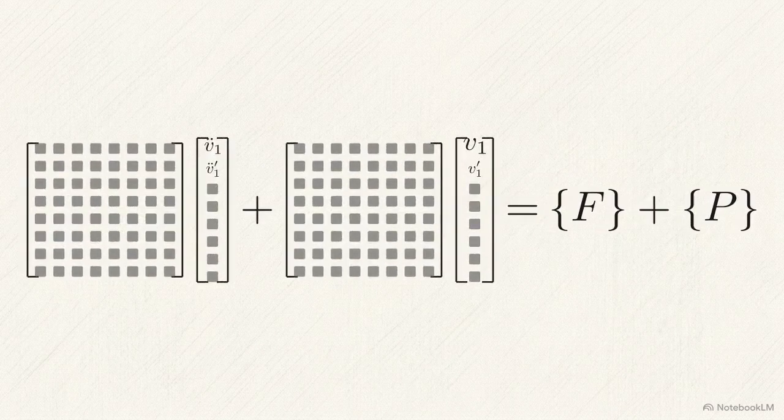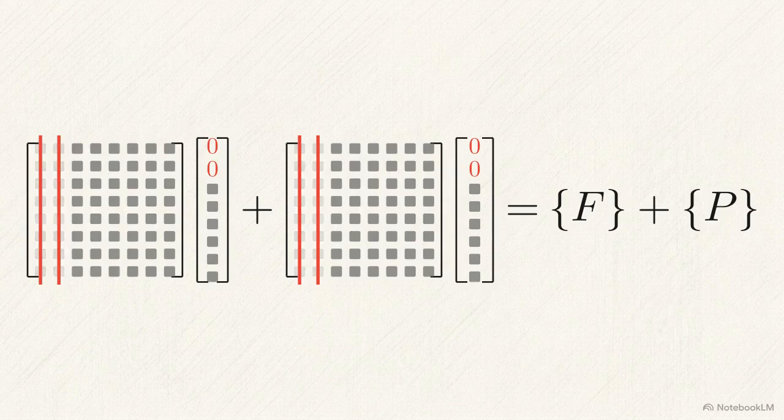We insert these new constraints directly into the acceleration and displacement vectors, replacing the variables in the first two rows with absolute zeros. The mechanics of matrix multiplication dictate that multiplying a matrix by a vector containing zeros completely nullifies the corresponding columns. Based on those zeros, we strike through column 1 and column 2 in both the global mass and stiffness matrices, dropping them entirely.